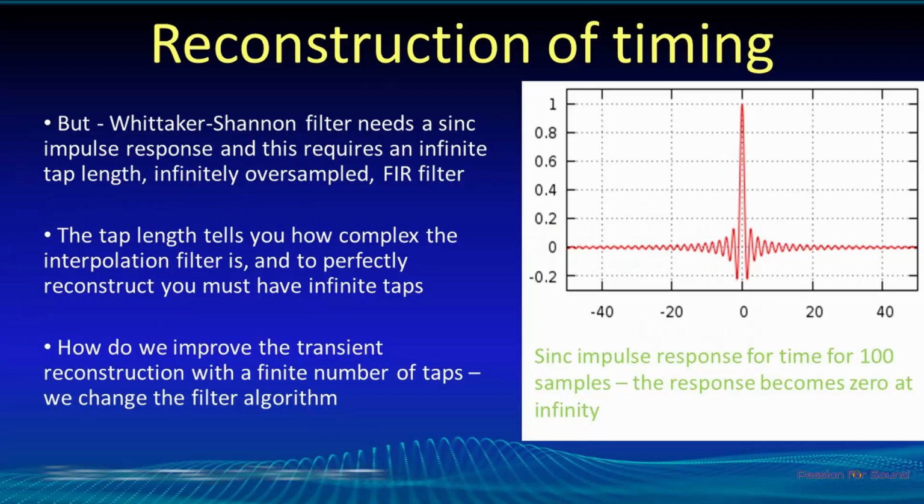Now, Sinc functions get really confusing for me, if I'm being honest. The research I've done is very technical, very mathematical. And so to boil it down, my understanding is that the term Sinc function is really just a mathematical function to understand how the DAC responds to a single pulse. So if you send in a single pulse, what will actually happen with the Sinc function is that you get the main sound wave output of the DAC, but on either side of the main pulse, before it and after it, you get a rippling effect of what's called pre-ringing and post-ringing.